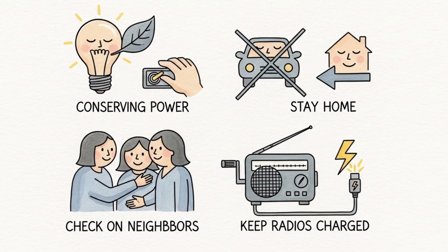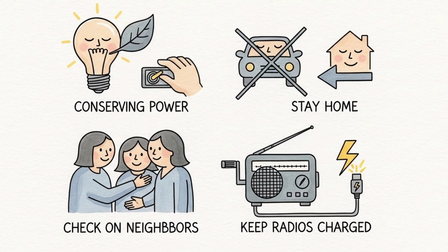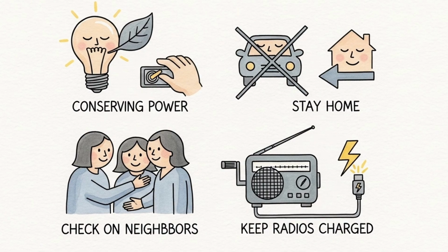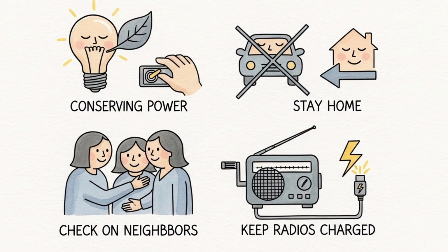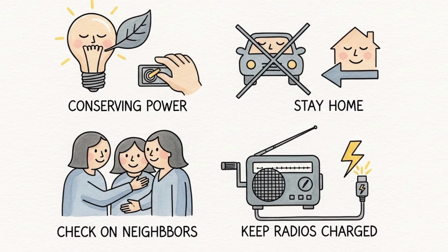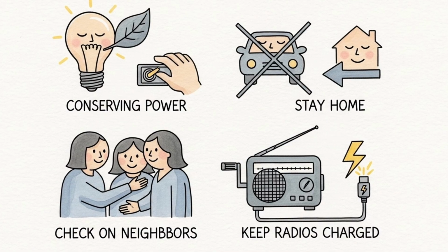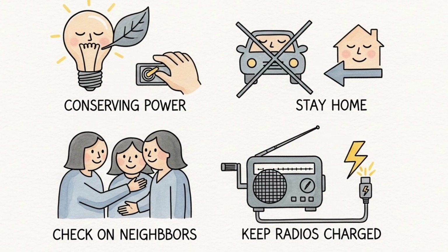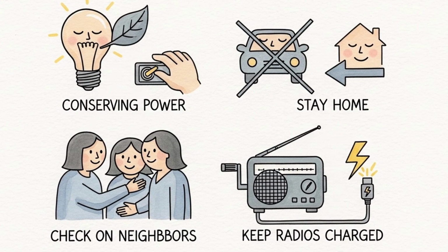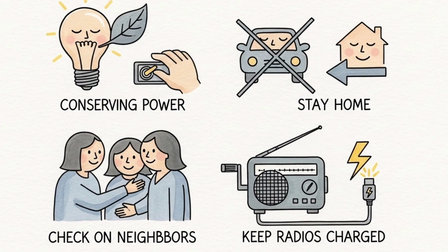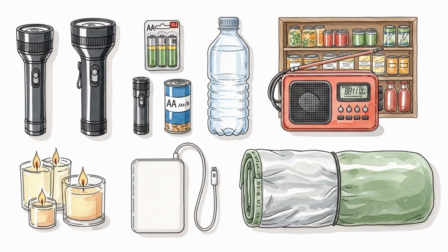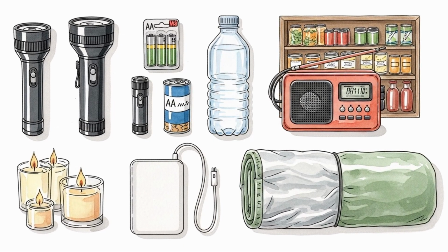Uplink commands may require repeats. Downlink telemetry rates are reduced. Some operators switch to low-gain antennas, which are more tolerant of pointing error but reduce data rates. Schedules move non-critical high-rate dumps to quieter periods. Automated link adaptation is enabled where available.